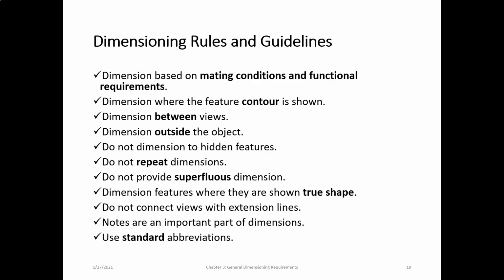Dimension features where they're shown in true shape and size, especially relevant for auxiliary views. Do not connect views with extension lines. I already talked about that. Notes are an important part of dimensions. And finally, use standard abbreviations where symbols are not applied.